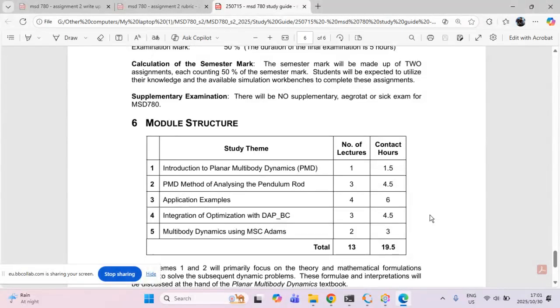And the focus over there was on the analysis and formulation that we apply to planar multibody mechanisms. We mentioned some compliance elements as well, so springs and dampers and actuators that we can have in a system. But most importantly, we considered the kinematic joints, which is the connectivity that we have between the different bodies of a system. So some of those examples were revolute joints. We also looked at disk joints, translational joints, all those kind of joints that enforce some sort of a constraint. So something that removes the degrees of freedom of your system.